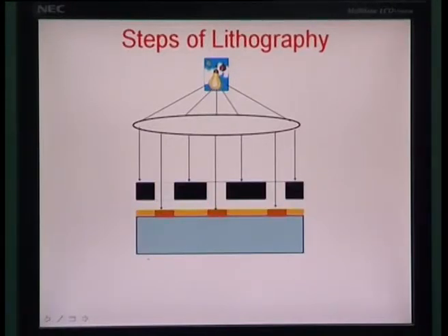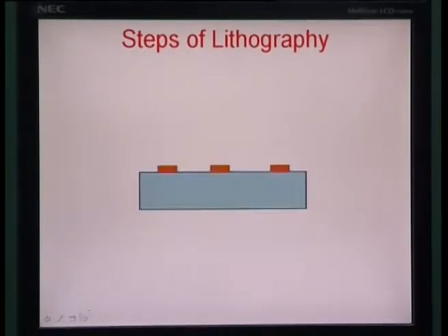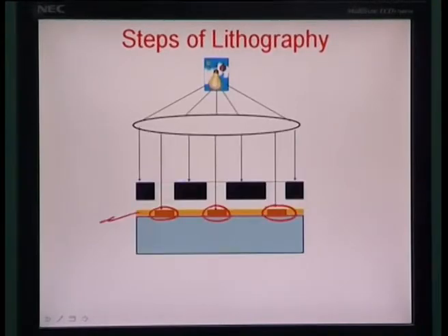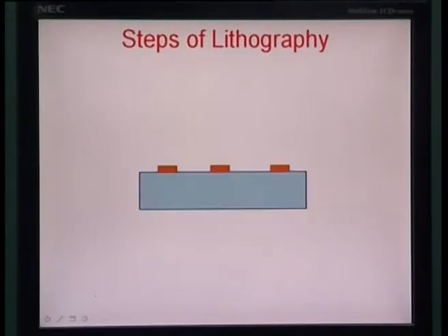Because the exposure is selective, you have zones of different chemical compositions developing. In case of negative resist they are cross bonded, in case of positive resist they are debonded. So if it were a negative resist, you could etch off the remaining material with the developer solution, and you get these features which were cross bonded and stayed back.